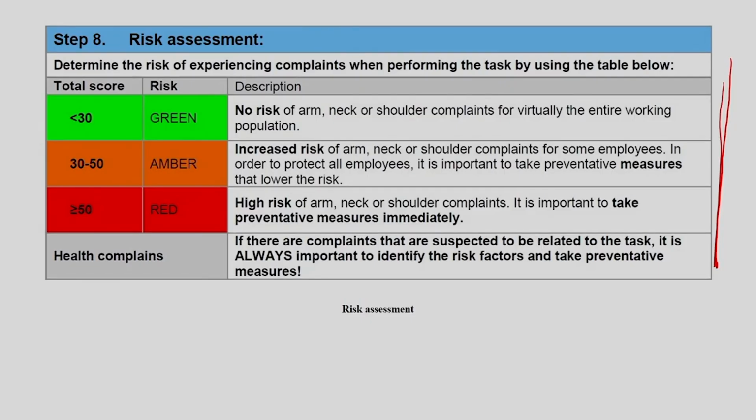If the weight limit of the manual handling is more than some 60 kg, then it is not possible to use this particular tool. For that case you need some kind of pulling, pushing, lifting, like the lifting equation or MAC or any other tool. This tool will not be applicable in that case.